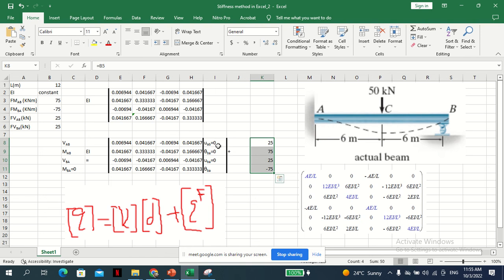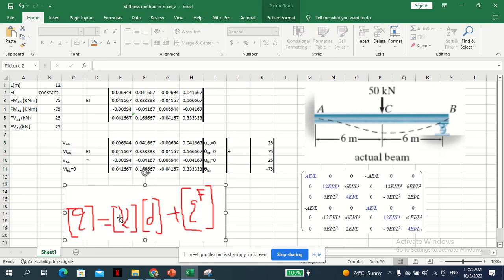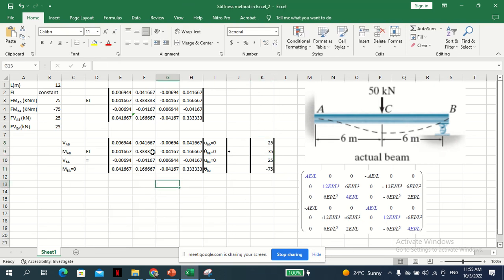So for this fixed end, we cannot have any displacement. There cannot be any theta because of the fixed end. Again, for a pin, we cannot have displacement unless it is prescribed. So that is 0. However, theta is not 0 because there is no moment. If there is no moment, there will be some value theta here. Okay, and of course with a fixed value. So you can see that if you are to solve, we have one equation here that is able to solve